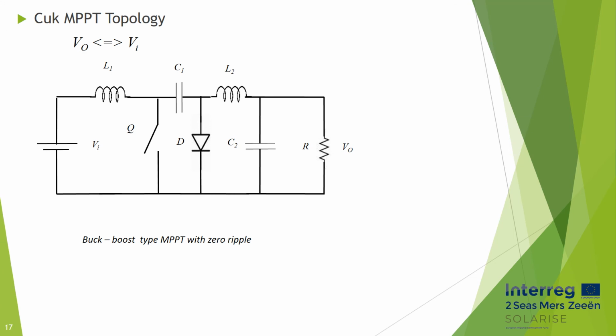For high-power applications, Cuk converters are more efficient. The Cuk converter is a negative output capacitive energy flyback DC-DC converter. It is developed from the basic buck-boost converter. The difference is that it uses a capacitor, not an inductor, for storing energy and transferring power. Main disadvantages of the Cuk converter are inverting the polarity of the output, besides the high current flow through the power switch and the diode.